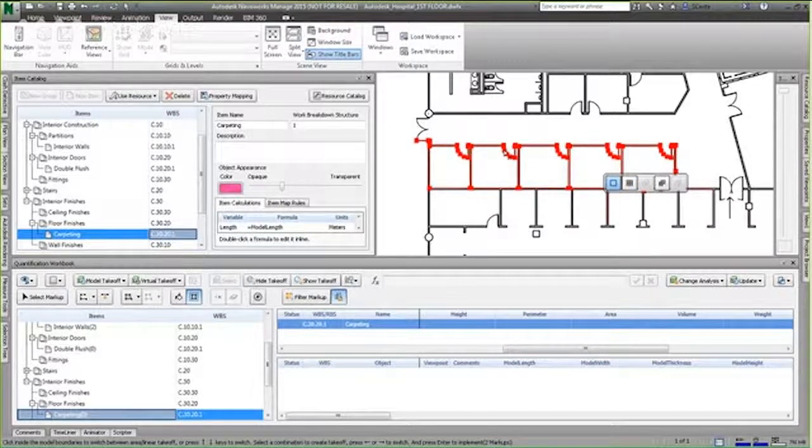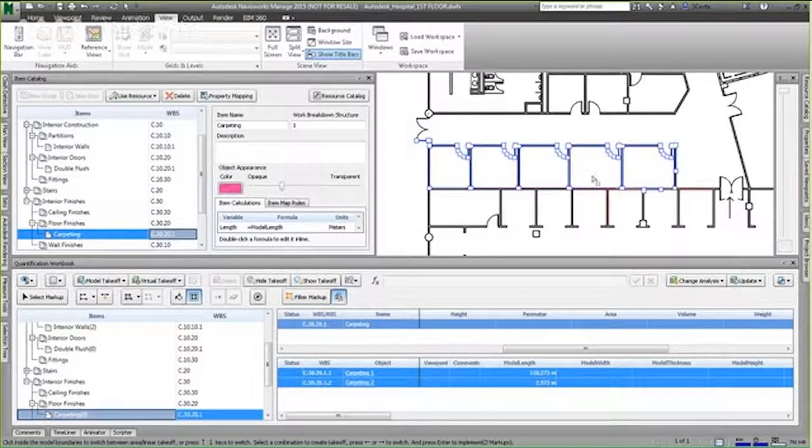Now, with these doors, and again, maybe Reed could type in later with the Revit, I don't know if it's a view thing that you can set inside of Revit so that you show the doors closed. My recommendation in general would be, if you're exporting from Revit, specifically for quantification, you might want to set aside certain views to facilitate that, right? Maybe off the bat you can disable some of the annotation, but I would imagine that you can set a particular view so that the doors show up closed so that you don't get that sort of quantification. That would be incorrect, right? If you still have carpeting or tile or whatever up to that location. Anyways, I'm just pointing that out so that you can become aware of how that gets quantified.